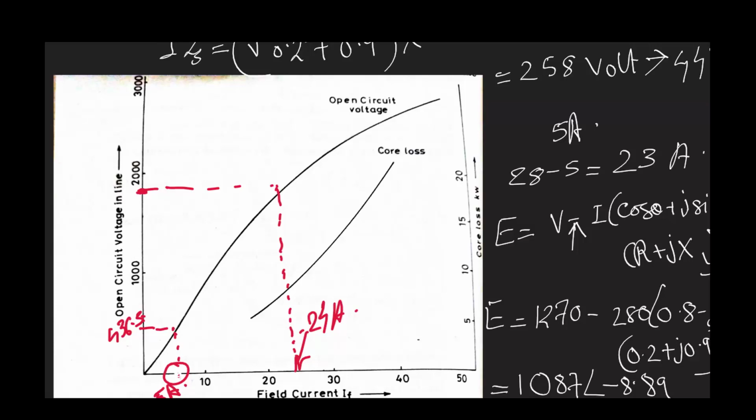So as per this book, the field excitation value is somewhat 24 ampere. Right. So this 24 ampere, and what is the full load armature reaction in terms of our field current, or let me make it clear, how much field current is required to counterbalance the full load armature EMF?